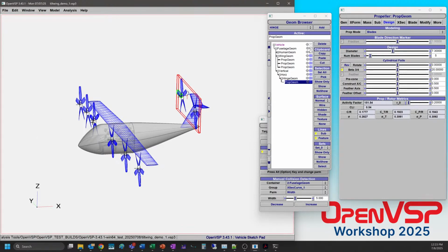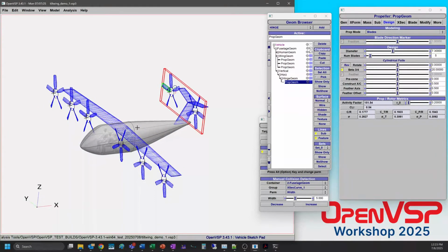you can put together a fairly complex aircraft that articulates, moves, is sized based on any number of things. If you want to go in and change the design variables to be something like disc loading, thrust, your wing loading, what's your gross weight, all of that stuff can also be done. But you don't have to go in and change individual components and then rebuild everything and hope nothing broke. It all still works. They're all individual watertight geometries. This whole thing will mesh. The whole thing is closed. And so that is never really going to be a problem for you if you do things this way.